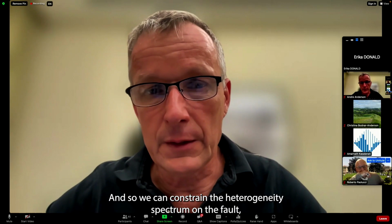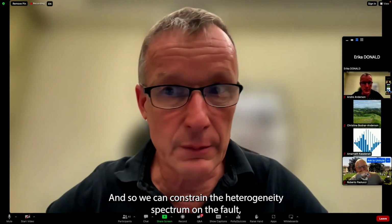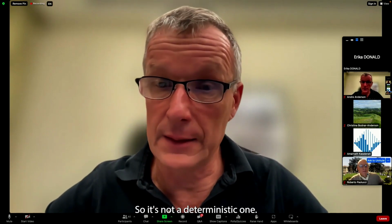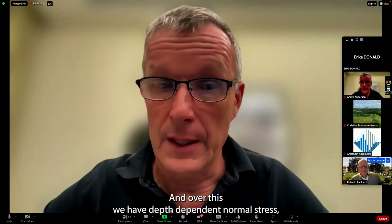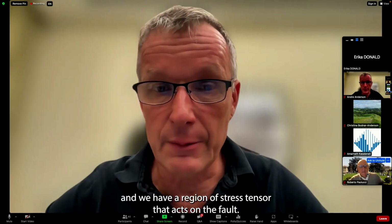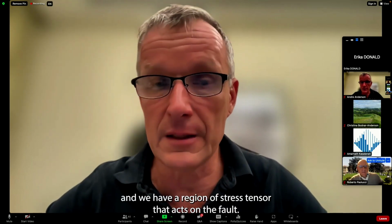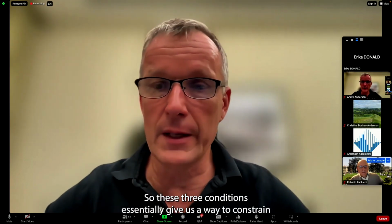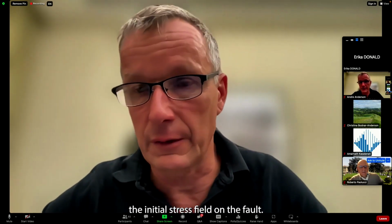And so we can constrain the heterogeneity spectrum on a fault, but it's a stochastic one, not a deterministic one. And over this, we have depth-dependent normal stress, and we have a regional stress tensor that acts on the fault. So these three conditions essentially give us a way to constrain the initial stress field on the fault.